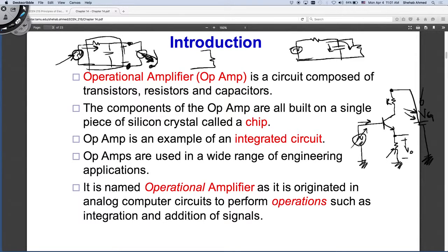You would like, as soon as your sensor value reaches a certain level, 3 volts for example, the current through this resistor to be such that it corresponds to a certain output voltage. I would like that to happen. So what transistors do is they act like a switch with a resistance in series, simply speaking. A controlled switch with a resistance in series. So what does this mean?